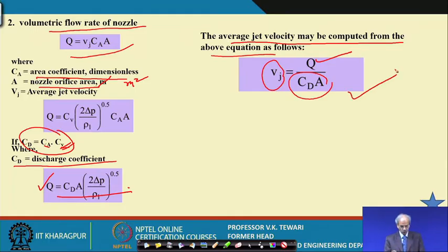If you know these details, you will be in a position to design a sprayer, and for a particular application you can select the pump with the pressure and flow rate that you want, whether low volume, ultra low volume, high volume, etc., and the type of application, whether it is for orchards or wherever. So, with this information, I think it is worth knowing and selecting, particularly with regard to sprayers.